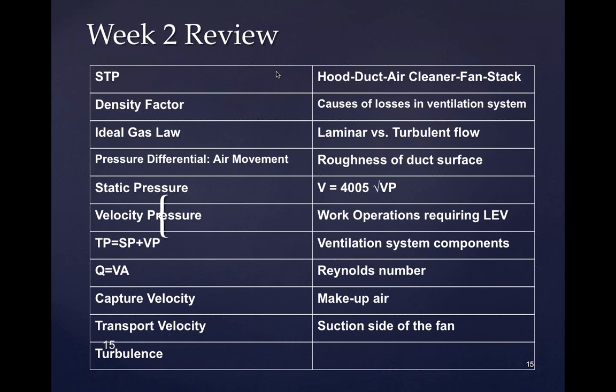Anybody know in the lab when you took the environmental lab where you used a centrifugal separator? A little bit smaller than this one. Well, impingers, yeah, but you used it. Remember, you did your particulate sampling, right? That little device that you put on there, that cyclone, was a centrifugal separator. It spins, the larger particles get spun out and they drop into the bottom.